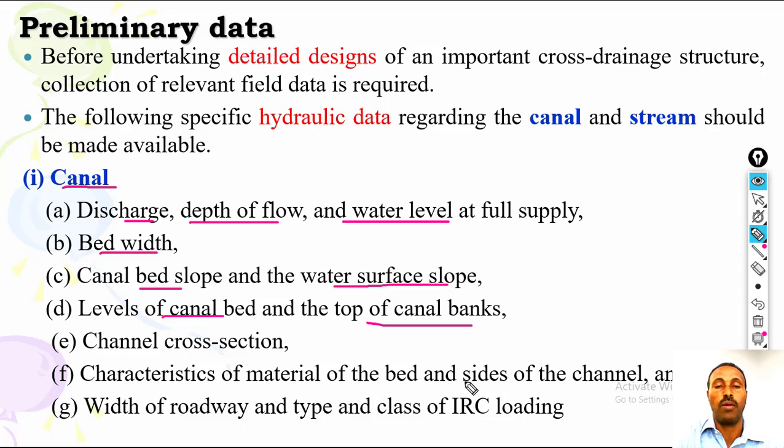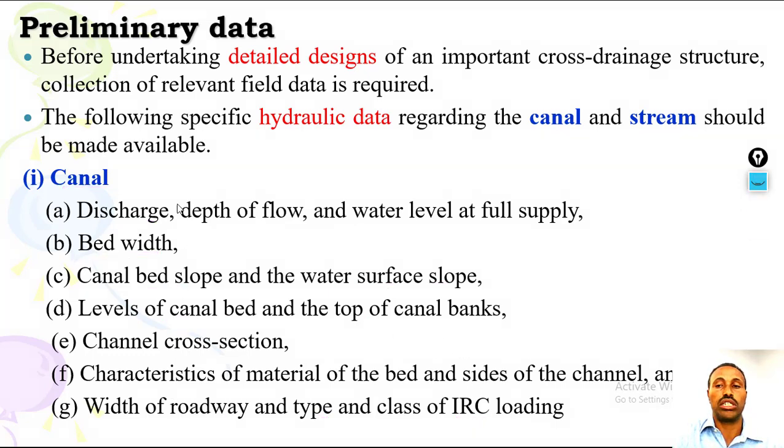So you need to know the material type of the bed of the canal, and the width of roadway, and the type and class of IRC loading for the roadway you may construct on the side. I think these are important aspects to undertake the detailed design of CD work for a canal.